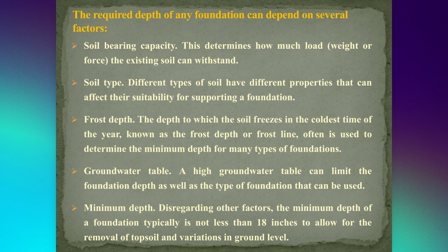The required depth of any foundation can depend on several factors. Soil bearing capacity. This determines how much load, weight, or force the existing soil can withstand. Soil type. Different types of soil have different properties that can affect their suitability for supporting a foundation. Frost depth. The depth to which the soil freezes in the coldest time of the year, known as the frost depth or frost line, often is used to determine the minimum depth for many types of foundations.